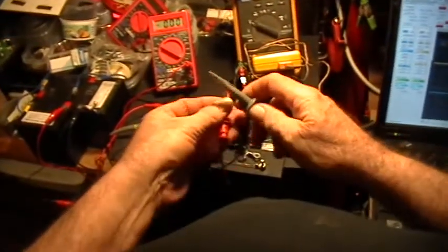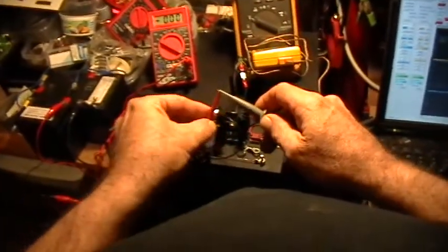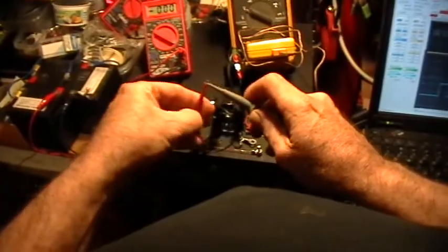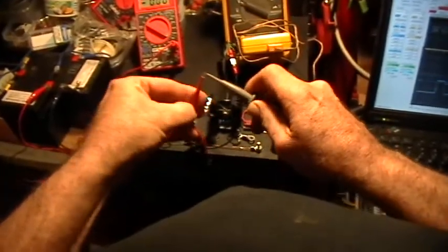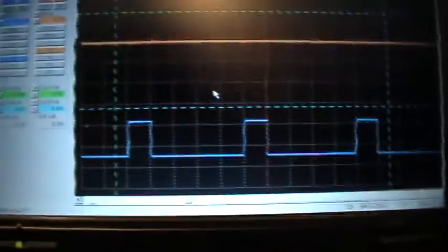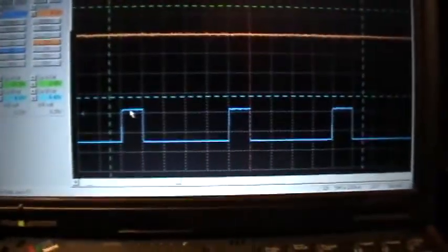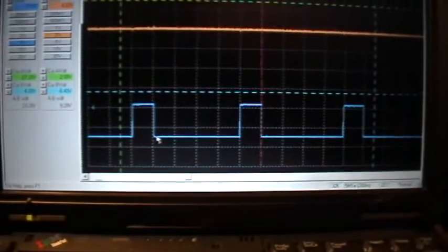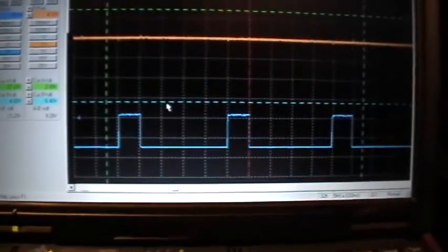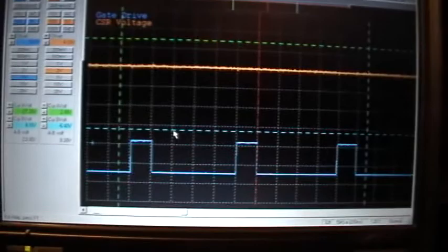You try this with one hand. I'm holding the camera under my chin right now. So you hook those together, like that. And then you go back to the oscilloscope and you read it. Okay? So what is the maximum value here? What is the minimum value here? And you can do that with the cursors.